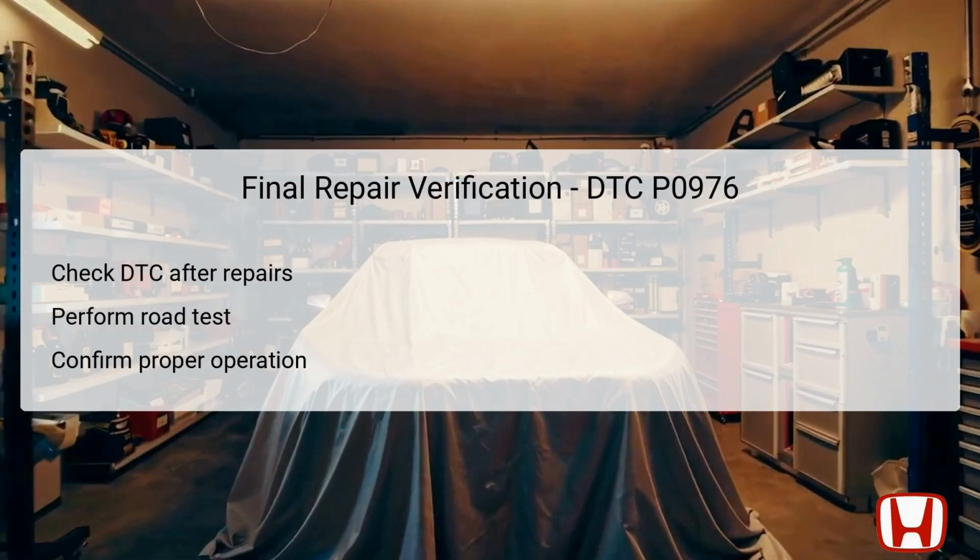Once repairs have been performed following the diagnostics for DTC P0976, it's essential to verify that the issues have been resolved appropriately. Begin by checking the diagnostic trouble codes stored in the vehicle system to ensure that P0976 no longer appears. Following this, conduct a comprehensive road test of the vehicle to observe its shifting behavior under various driving conditions. This test is crucial for confirming that the transmission is operating smoothly without any symptoms of delay or erratic changes. Additionally, confirming proper operation will provide assurance that the repair was successful and the vehicle is now ready for safe use.